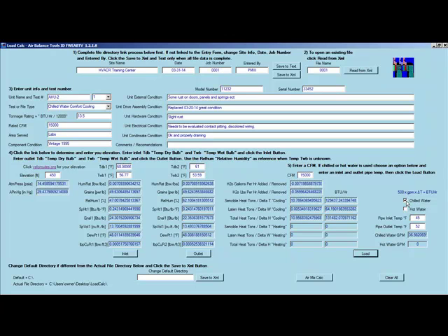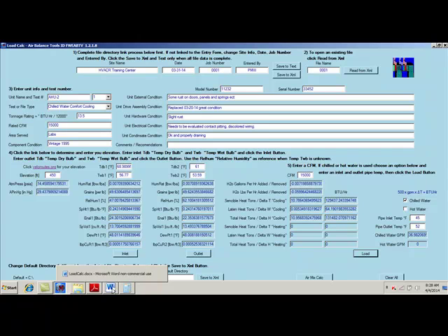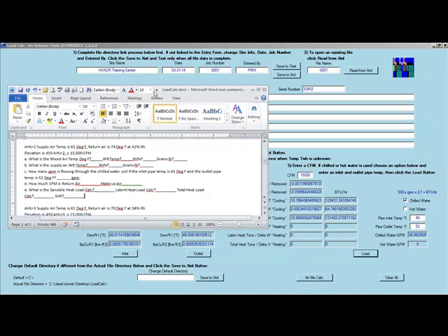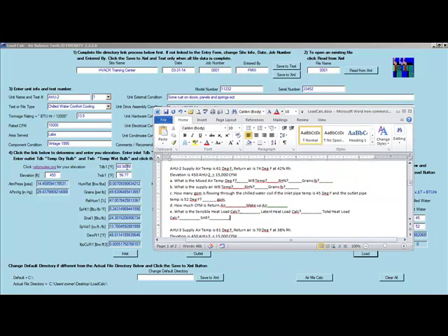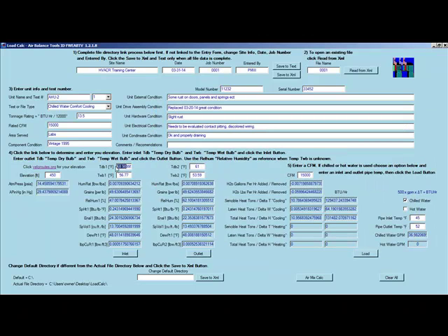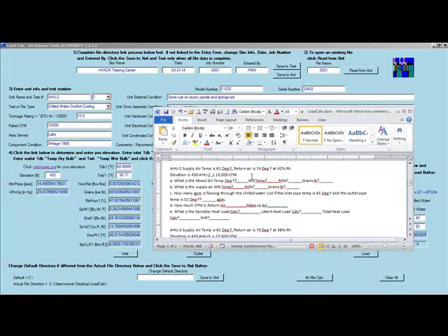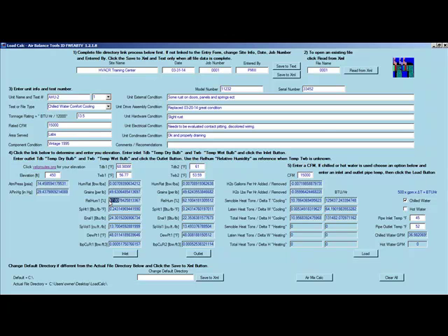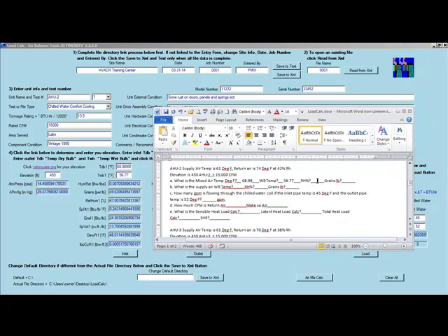And now we have our data. We've got our chilled water. We have our GPM at 36.98, or we could say 37 at that point. So let's go ahead and add our data into here. What's the mixed air temperature? Well, our mixed air temperature is, or we could say 69, either way, right? So there's our mixed air temperature, our wet bulb, our RH, our grains of moisture.